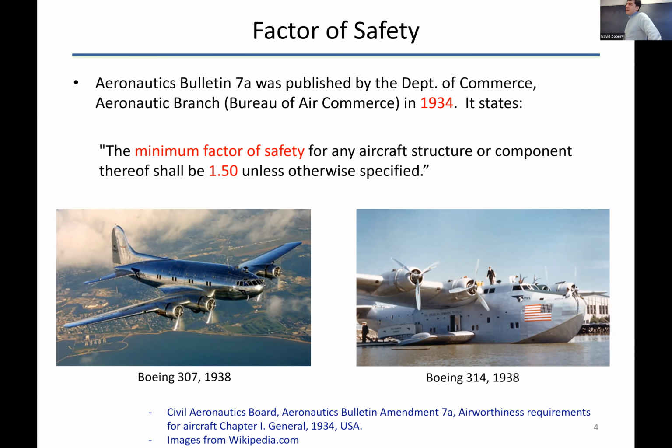Yes. At that time, the ratio between the ultimate strength and the yield strength of aluminum was 1.5. Let me do a sketch. This is the stress-strain curve of aluminum at that time. It has changed since. If you load the material in tension, sorry for my drawing, there is the elastic region, then yielding, and then the ultimate strength. The ratio of sigma ultimate to sigma yield at that time was almost 1.5. The material has changed ever since.